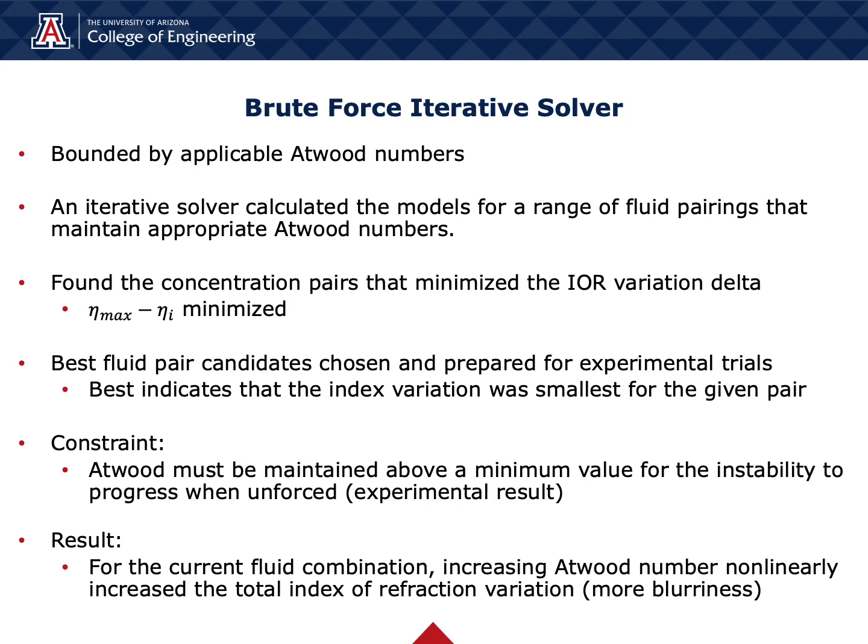First, there is a maximum achievable Atwood number for any fluid pair combination. That sets an upper limit on the problem. Second, there also exists a minimum Atwood number for the combination. A very low Atwood number means that there is a very small difference in densities for the fluid combination. Too low of one will prevent any development of the Rayleigh-Taylor instability, since the Rayleigh-Taylor instability is driven by this density contrast. That sets a lower limit for the solver.